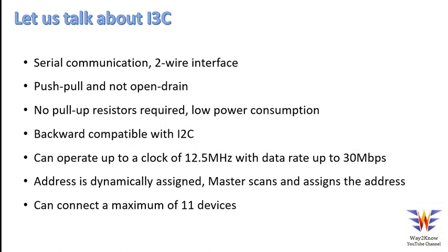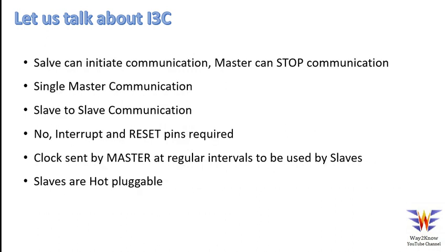So that is one important thing, whereas in I2C the address is fixed, where we go through the internal address register and then use the pins that are there by hard coding those specific address bits. And here we can connect up to 11 devices maximum, which is again depending on the protocol deficiency. So this has to do more with the protocol coping up with the number of devices. At the moment it is restricted to a maximum of 11 devices.